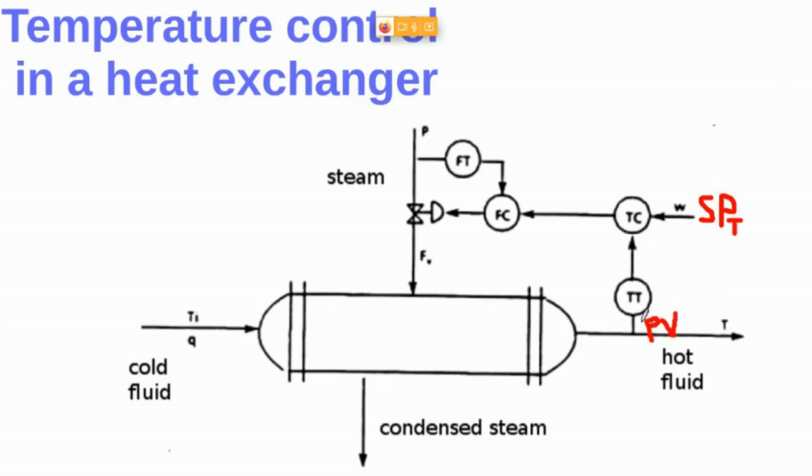This signal in here is the process variable for the temperature, right? Here we have also the process variable, but it's the measured process variable. So you can put a star in here to make the difference between the process variable. These are the degrees, right? So it's the real temperature, and this is the voltage that explains this temperature, right?